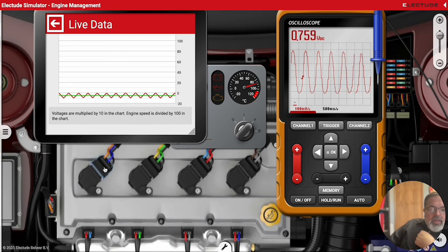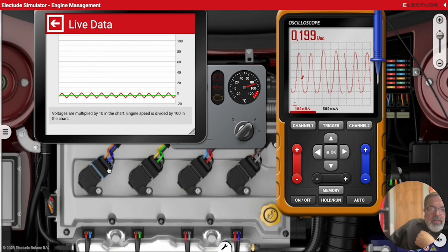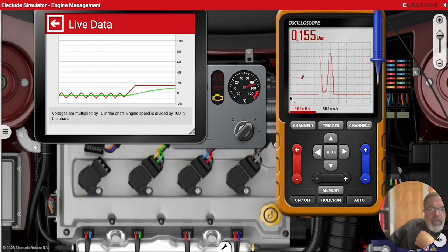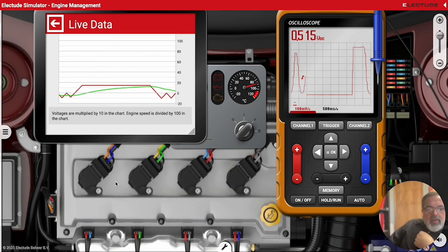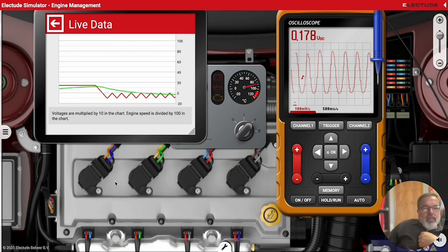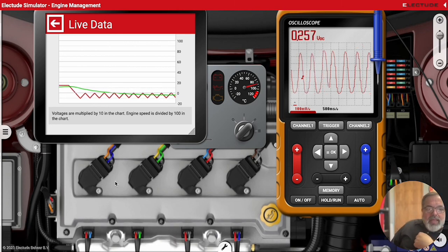So we should see the same result, at least initially till it figures out there's an open circuit. It'll probably initially give it more fuel, as you can see, and it actually goes lean, because even though there's a ton of fuel in the exhaust, it's going to show lean because it can't see the fuel, it can only see the oxygen.